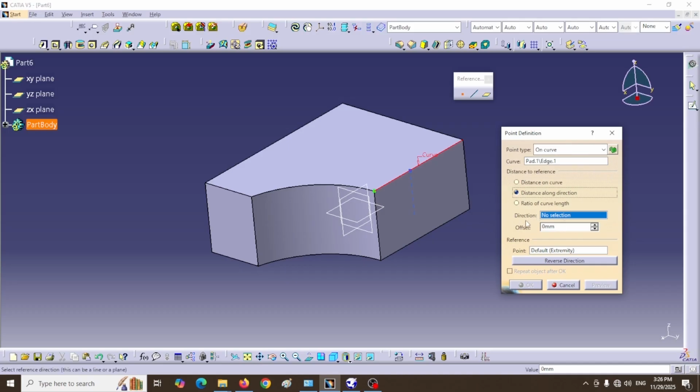Now another option named direction appears. The framework in front of it is blue and waiting for a direction to be defined. In this mode, the measurement is done along the defined direction. Note that you can't define just any direction. For example, if I click on one of the vertical lines of my volume, an error will appear.